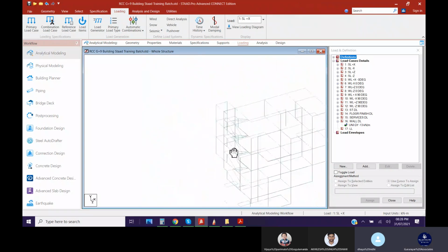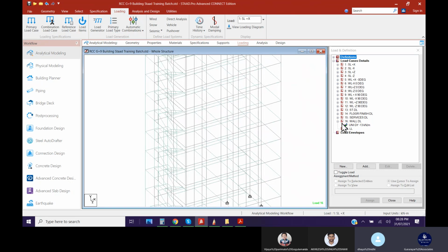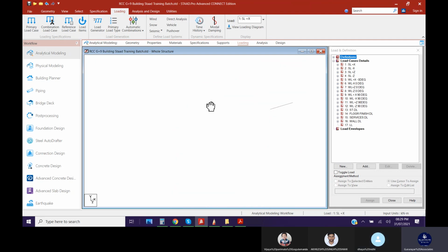Suppose you need some wall load here. Anyway, we added wall load here, 13. 13 means for the entire height. So it is okay, no problem. But this beam is a dummy beam. Not much, the same beam is going to give it. No problem, so no need to separately add something. Dummy beam means just to take the weight of the slab and transfer. Wall load, yes, of course it will come, but it is going to transfer to both sides. If you apply 6.5, 6.5 separately for all locations, that is good also. I'm not saying that is bad. So you can split if you want.